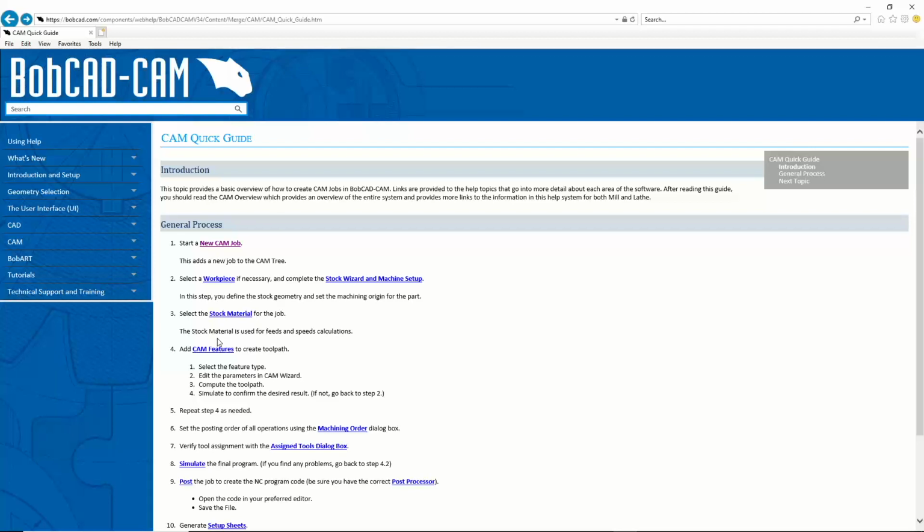Now you could, as you work through your tool paths, create tools and then go and mount them, which isn't a bad idea. And I'll probably end up doing that for a few tools. But I do recommend at least getting the majority of the tools, the tools you plan on using the most, into the tool crib first.